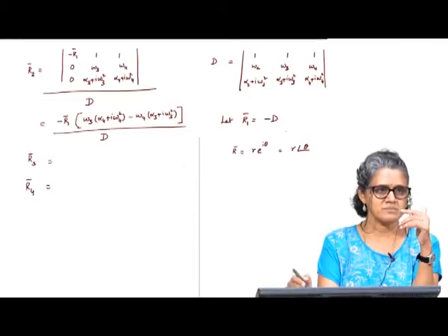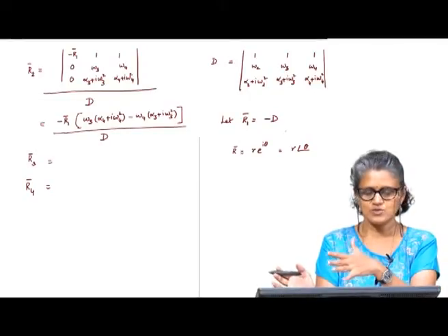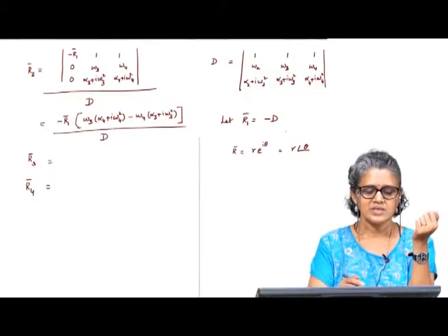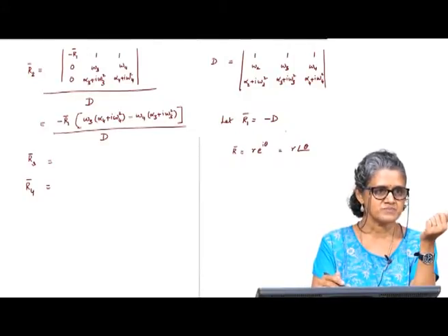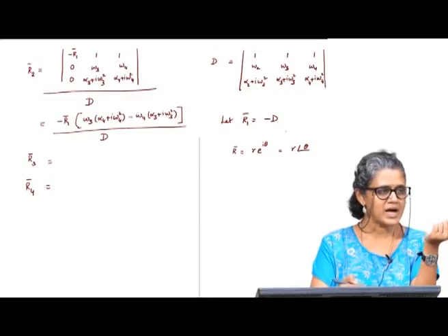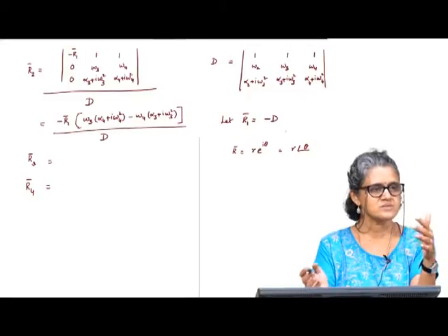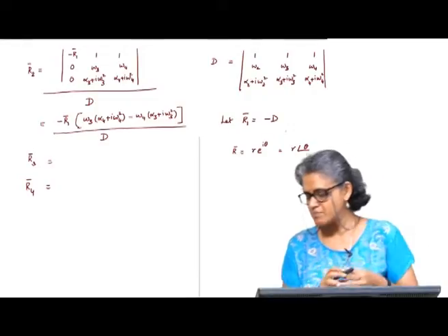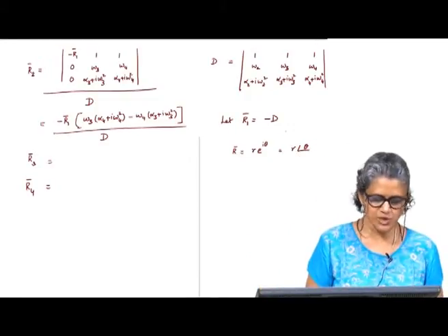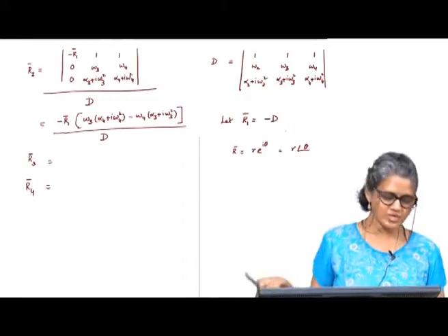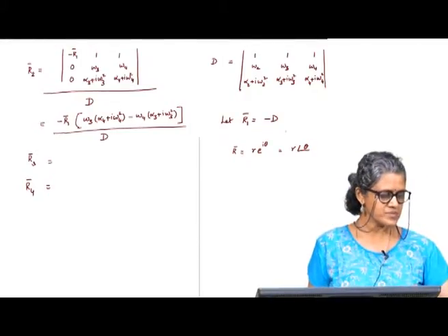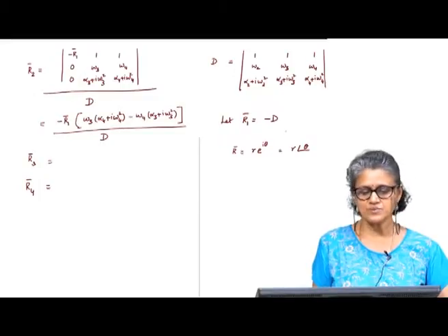I choose some R1 to match. So, if I choose it to match the denominator, then my calculations become simple. So, I can find an R2, R3, R4 in this manner, and then of course, once I find the linkage, we will do the example which will show you what you will get when you solve it this way, and then how you would get the configuration that you desire.